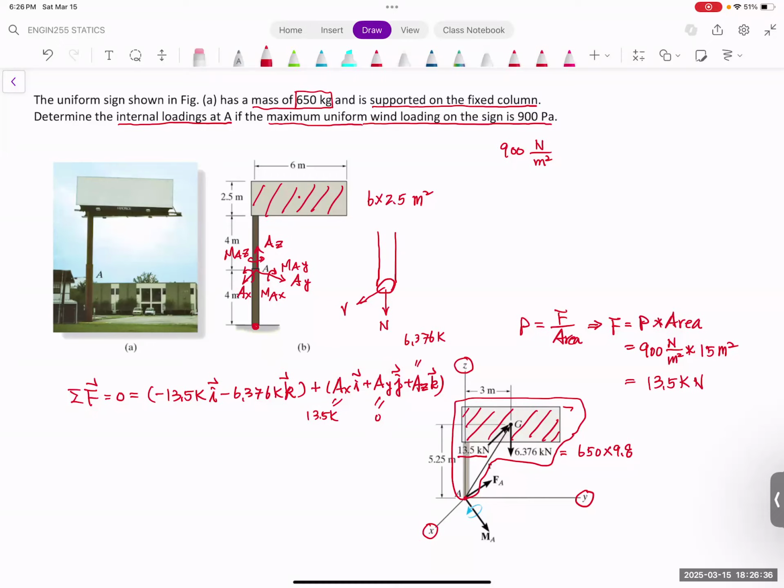So you have a normal force going outwards, that's positive. The shear force is the force that tends to make it rotate. Looking at the top one, it will tend to make it rotate in a clockwise direction. So the V is going to be a positive number as well, and this one is going to be 13.5 thousand.